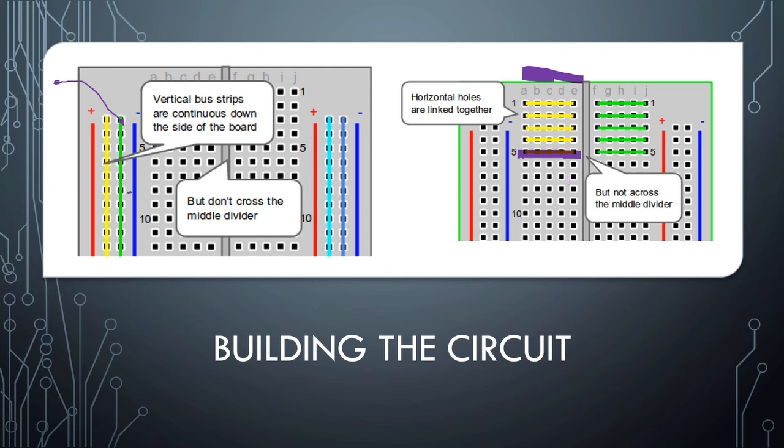What we would want to do to properly connect it is to span between linkages. So I would put one leg here, and then I would probably come down to wherever it fit comfortably, and I would plug the other leg in here. So my resistor would be spanning two different linked lines. And that's what you want in a component. The same component generally does not occupy the same line unless it's a push button. Sometimes it does. But my resistor would be here.